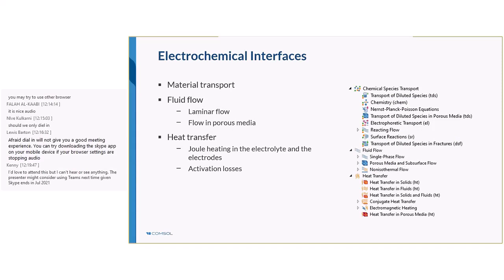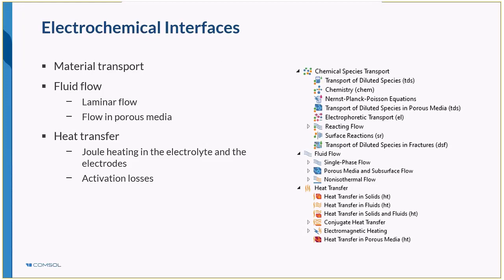So the way COMSOL represents physics is to use what we call physics interfaces. These interfaces contain all of the necessary domain and boundary conditions predefined for the representation of a certain physics. The corrosion module and the core COMSOL Multiphysics package together include the functionality to represent species transport in free and porous media by diffusion, convection and migration using the Transport of Diluted Species interface.